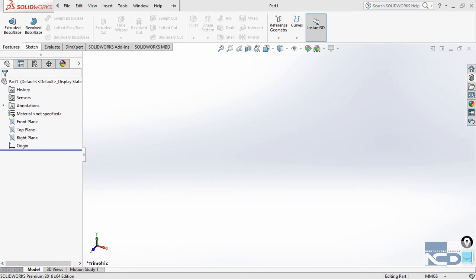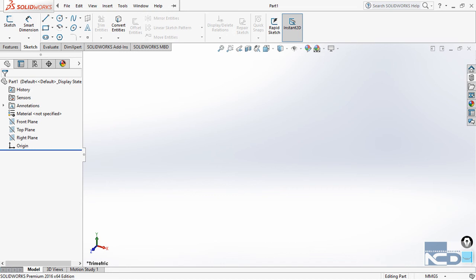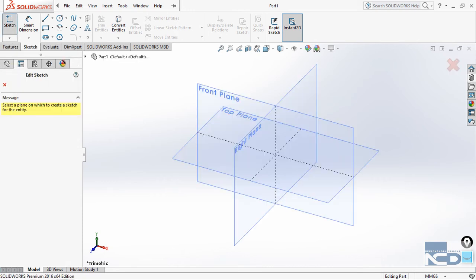For that we are going to select the sketch, so let's click on the sketch from here, and then it asks you to select the planes. So these are the planes that the steps are talking about. Right now you just have to select the top plane, as we have no such information available regarding these planes, how to use them and all.